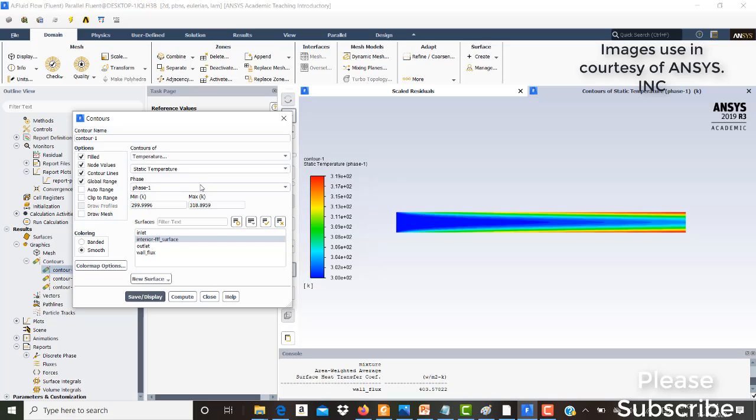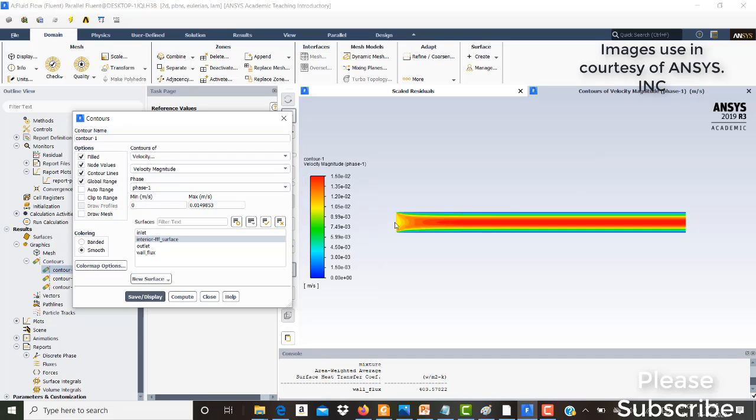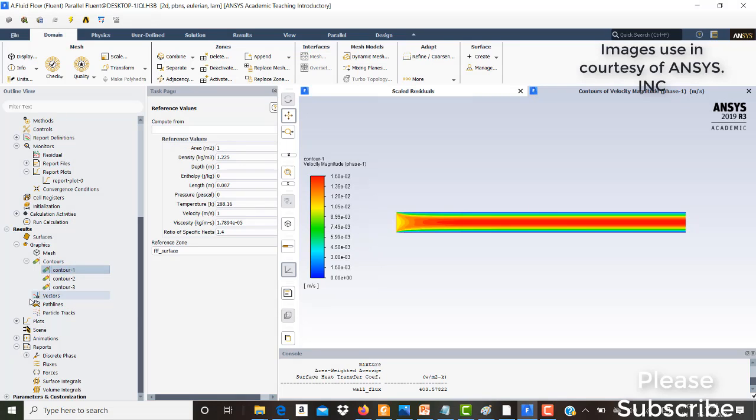And what else can we take? Maybe you can check down. So you can check this is the hydrodynamic boundary layer that is being formed, and it is just taking some time to get fully developed. After some time, it has been completely developed, and the profile is a parabolic profile. So if you want to check the parabolic profile also, you can check here.